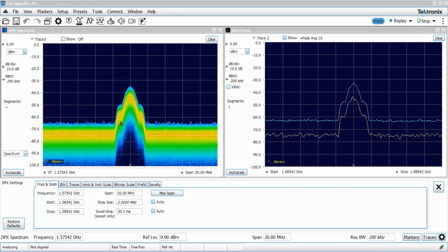It has a carrier, code, and data. All of them are modulated and transmitted. Now this is the peak power I'm sending, and this is the average, because there is modulation and so on. And you see the center frequency here is 1575.42 megahertz, and there is a 2 megahertz bandwidth here.